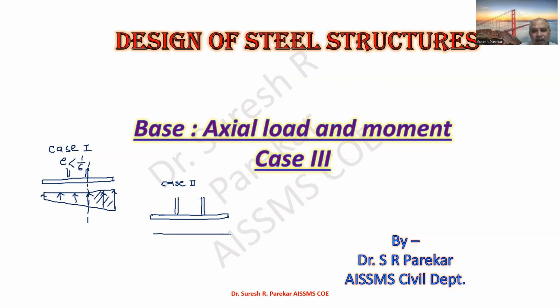Now what we have changed in case 2, try to understand. This portion goes up and this is tensile, but it is a very small portion, so we neglect it and consider this pressure distribution diagram. We find the bending moment again and then calculate the thickness.